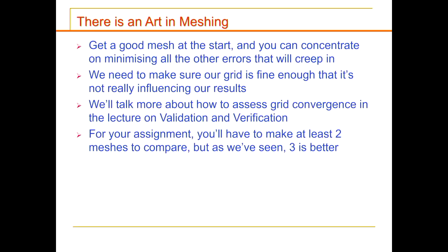If you resolve the flow of interest of the problem, you will definitely get a good solution. That's what we can say definitively. That's why we talk about fine grids, fine meshes, concentrating your mesh to the flow regions of interest.